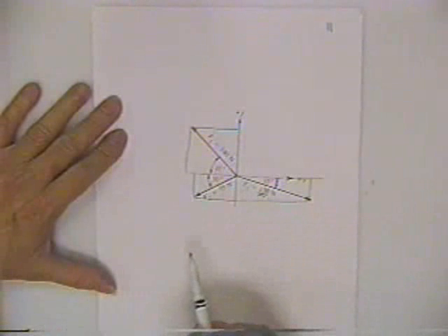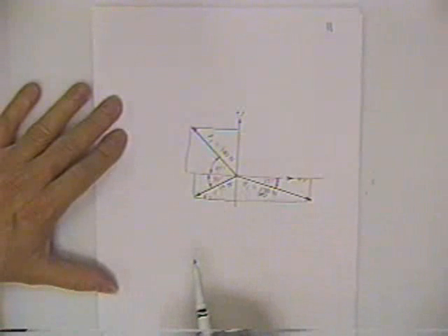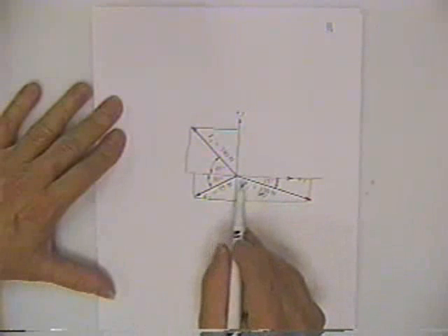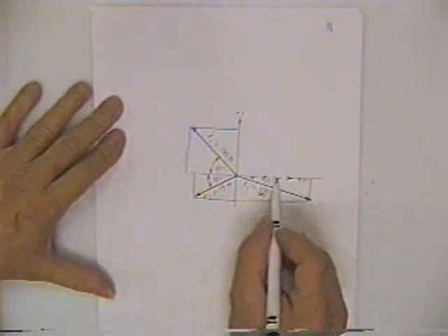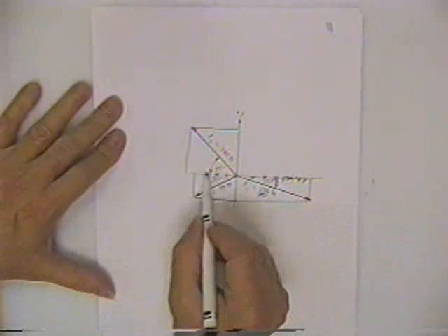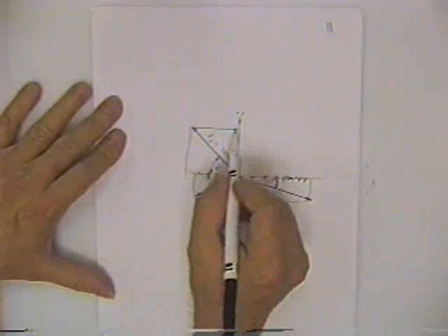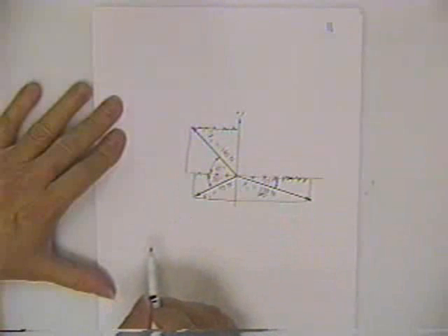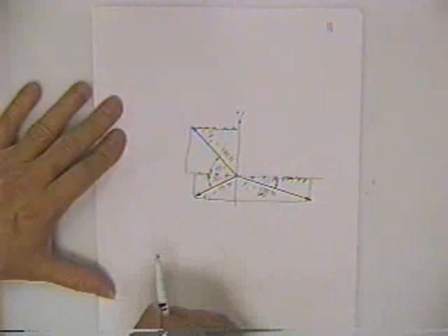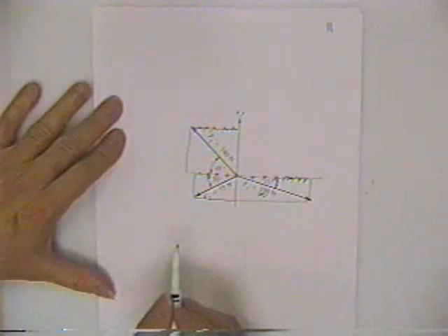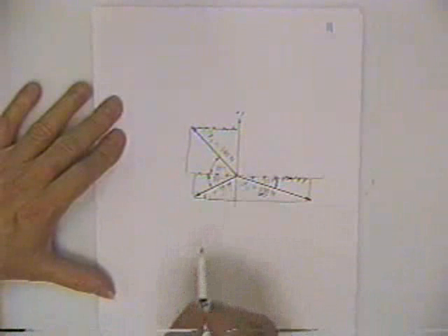And I don't care if we work out those numbers as long as you know what we're doing here. You'll then be able to add this particular horizontal force, subtract this horizontal component, subtract this horizontal component, and the resulting sum of those three numbers would be the total horizontal projection of one single resultant for these three forces.